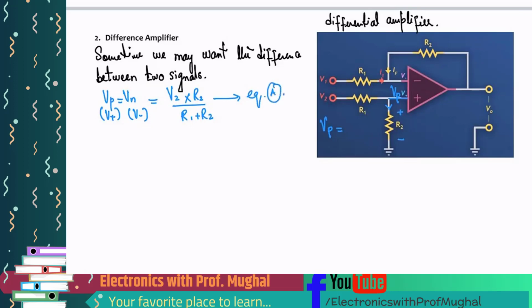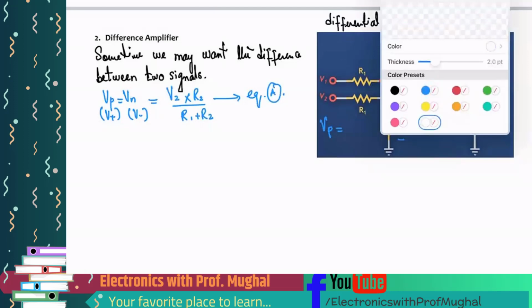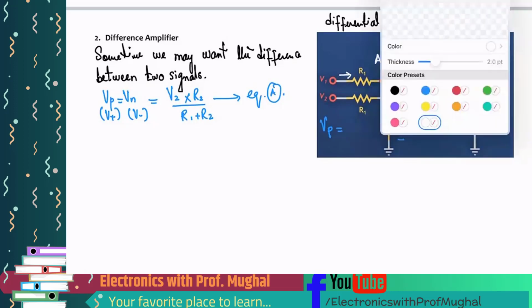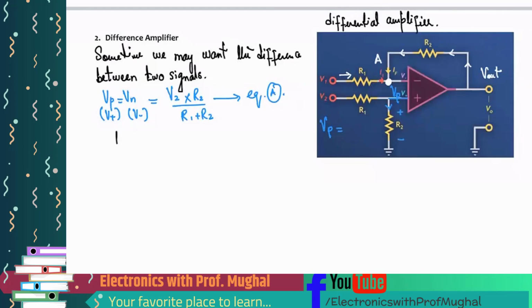Okay, now we're gonna apply the same thing. Now we're gonna apply KCL at this node right here, at the negative terminal of the op-amp. Remember you got this Vout here, right? You have some current IF going into this node. You also have some current flowing past resistor R1, and of course you got IN going into the negative terminal. So give me an equation. Say this white dot right here represents node A. What is the KCL equation that I'll get?